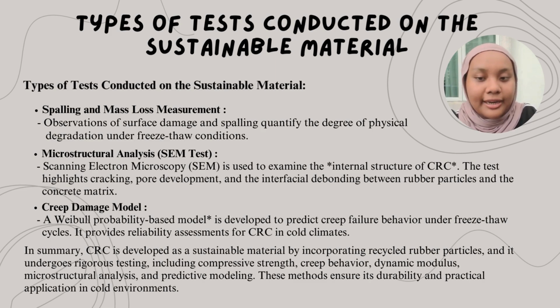So, in summary, CRC is developed as a sustainable material by incorporating recycled rubber particles, and it undergoes rigorous testing including compressive strength, creep behavior, dynamic modulus, microstructural analysis, and predictive modeling. These methods ensure its durability and practical application in cold environments.